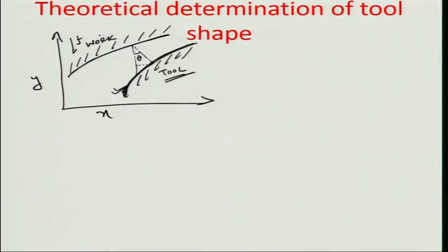Okay, so this really is the component design requirement which has been given. You already know what you have to machine through the ECM process, and let us assume that there is a functional relationship y equal to phi x, followed by a two-dimensional curve which is representative of the surface. So we are only doing a 2D analysis here, okay. But obviously this can be extended to 3D. We'll probably try and solve one example where we'll do it in 3D as well.